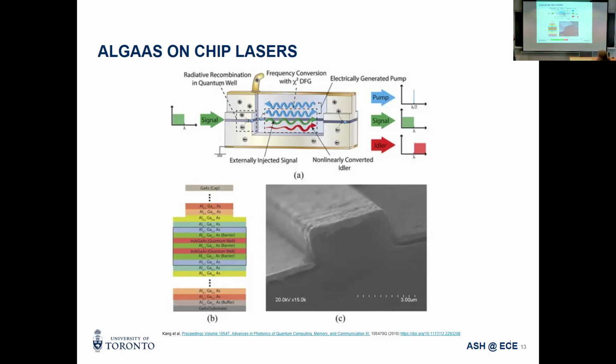Usually they're lossier compared to a straight silicon ring, but because these scatterers are resonant, we end up getting a higher Q and higher field at the smaller scale. So that's why we are looking at using these compared to conventional silicon.